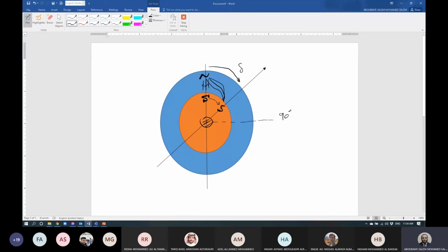And this is going to make something called desynchronization, or loss of synchronism of the machine, okay, due to the increase in loads. تمام. For that يا شباب, we have to keep our machine stable. How to keep our machine stable? Avoid reaching delta equal 90.